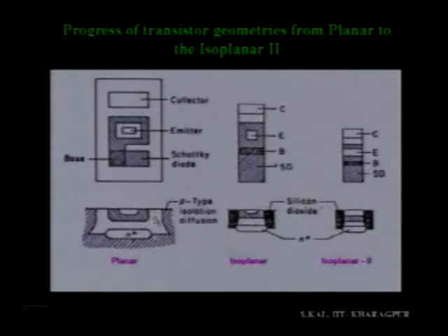So a lot of lateral space of the transistor will be consumed by this isolation diffusion region as well as the deep collector region, because of the long time diffusion. That means in this sort of structure you have to allow a lot of space between the isolation and the base region, which is not required in the second structure.